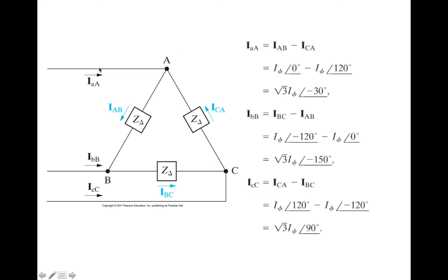then convert the impedance back. This uses an important principle from circuits 1, and that's the principle of terminal pair equivalence. So what I'm really saying is, I can break this circuit right here. I can pull out this delta connection, replace it with a terminal pair equivalent, and looking in this direction, you don't know the difference.